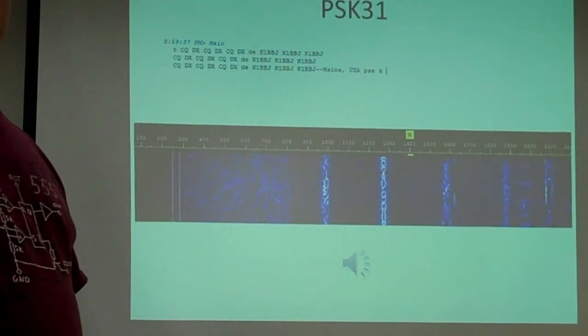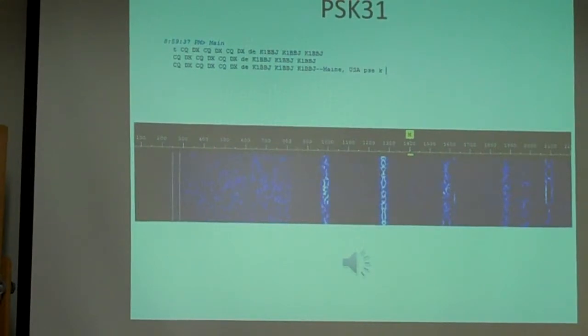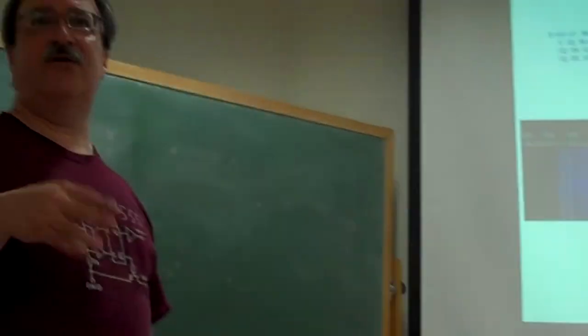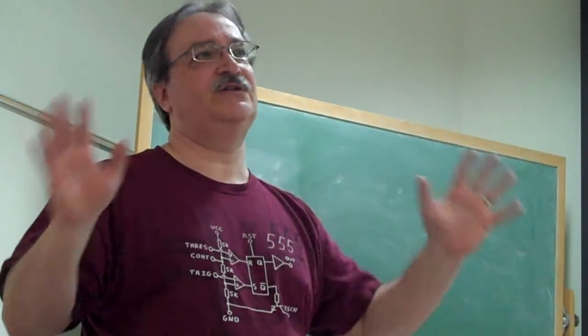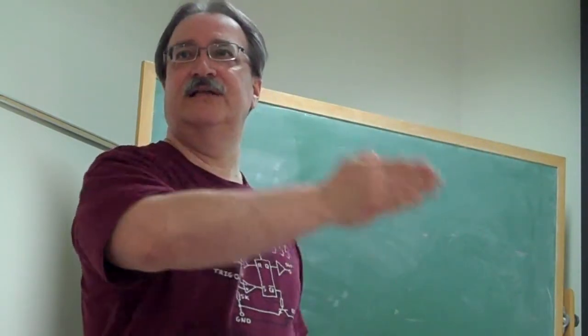If you could note, you don't touch the VFO knob on your rig. This is all done. Correct. Yeah, that's a great point. Unlike CW, for example, or sideband, where you tune in, you stick your VFO typically in fast, coarse tune mode, effectively, right? At 14070 or what have you, and the 2400, 2500 hertz that you work in is all done by the software. So you never touch the VFO after that. There's no tuning around, it's just point and click in the waterfall.